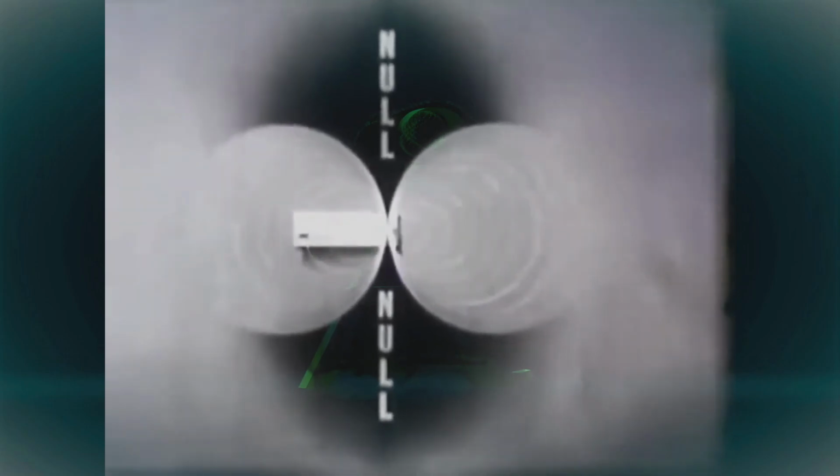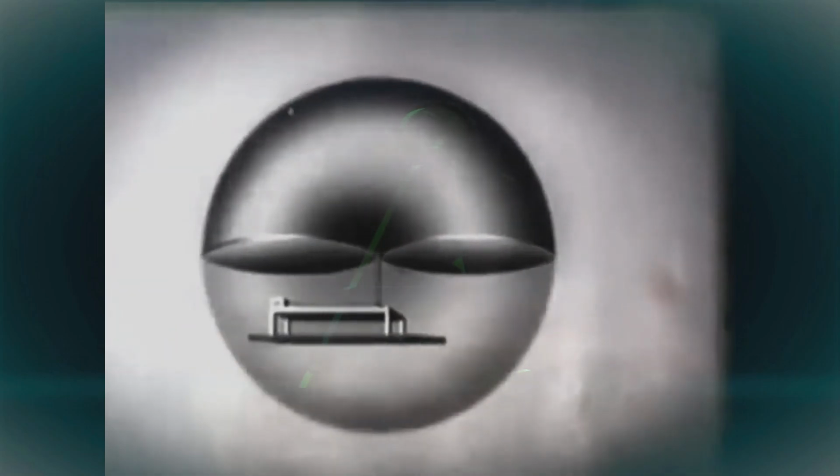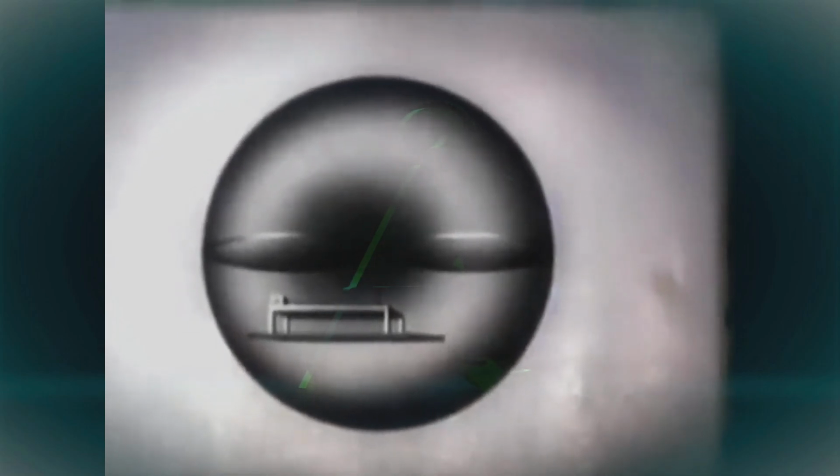The shape of this pattern indicates areas of no radiation or nulls along the axis of the antenna. A receiving antenna placed in a null area would be unable to receive a readable signal. Moving the receiving antenna into the radiation field, it will start to pick up signals that increase to maximum strength when the receiving antenna is broadside to the transmitting antenna. By plotting a graph of the signal strength received, we get a cross-sectional view of the radiation pattern. A three-dimensional representation of the pattern looks something like a donut. Regardless of its physical length, any half-wave antenna will radiate this type of pattern.